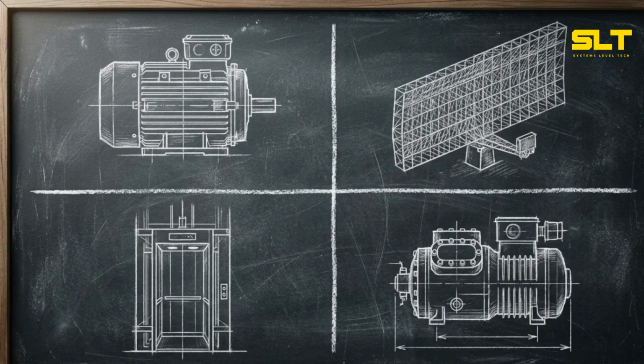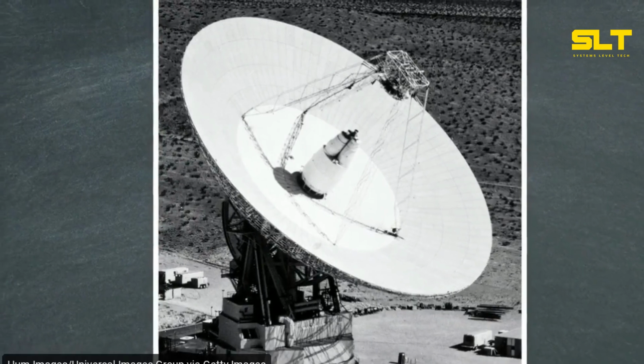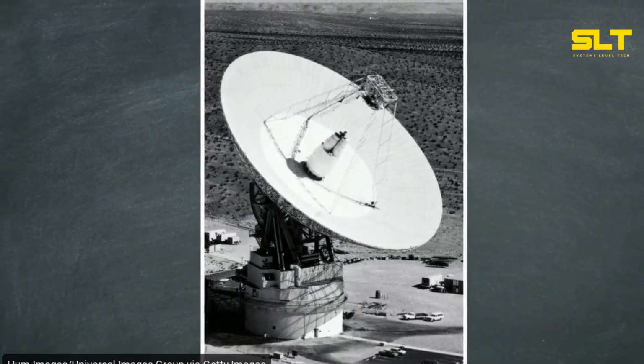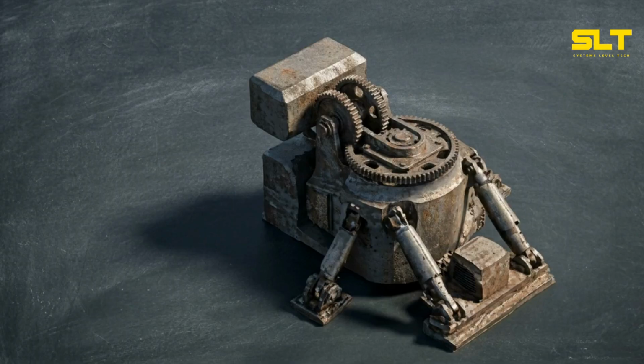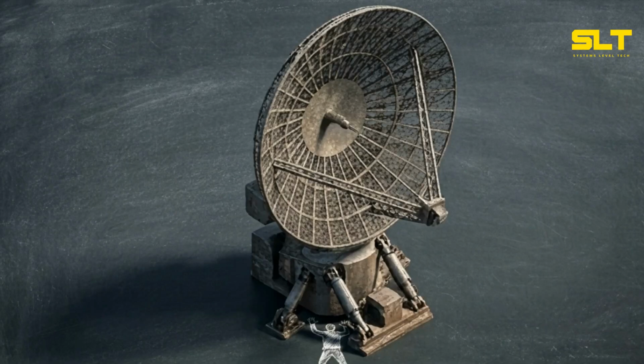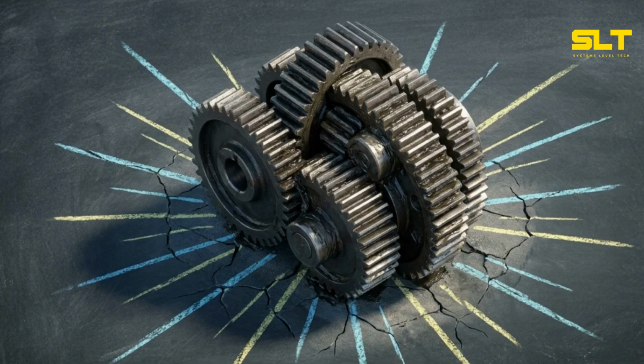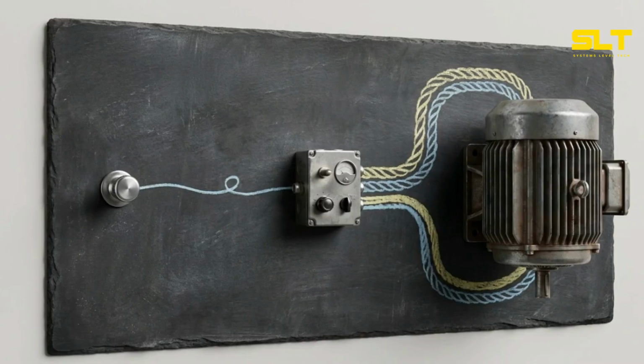We build these complex, self-correcting loops to solve 4 specific physical constraints. To see these constraints in action, we can use a massive structure like a deep space radar antenna as a case study. The first specific constraint is power amplification. Imagine a human operator trying to manually push this multi-ton dish to a precise coordinate. The human input, physically turning a small command dial, contains only a tiny fraction of the mechanical power required to move the steel. By placing a control system in the middle, electrical motors read that weak input signal and amplify it into massive torque for the output.